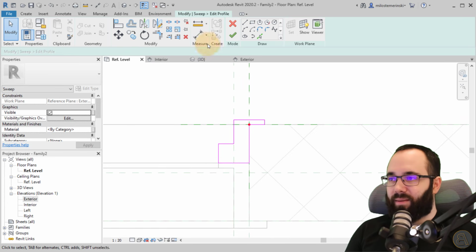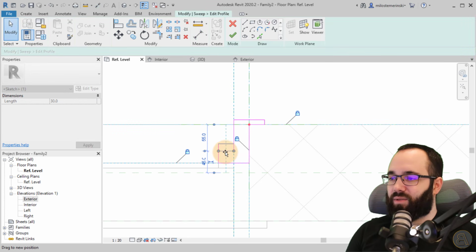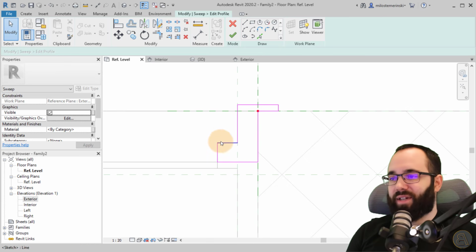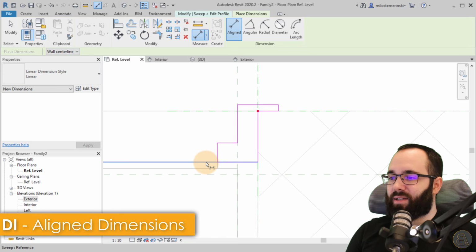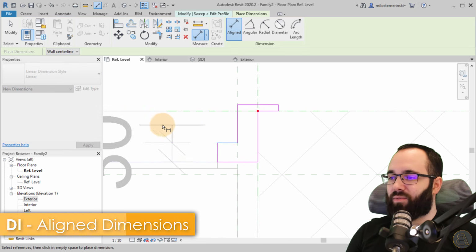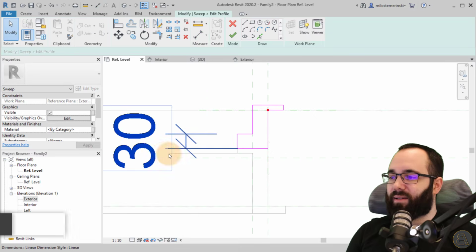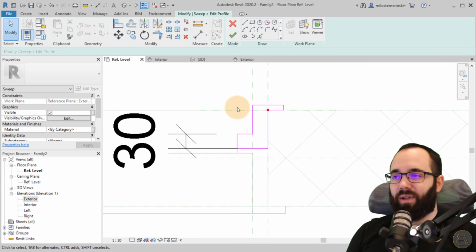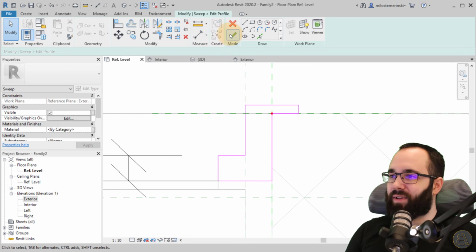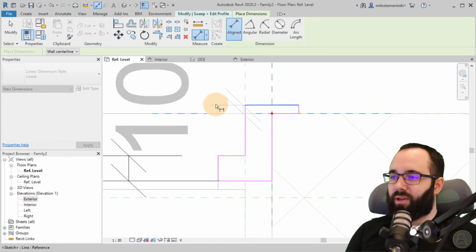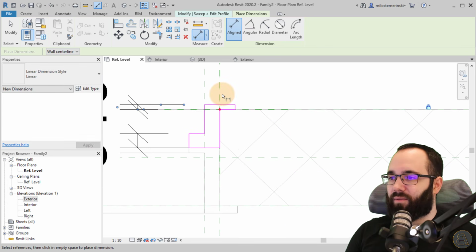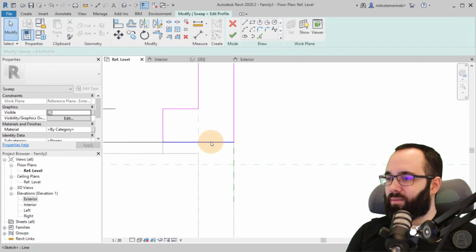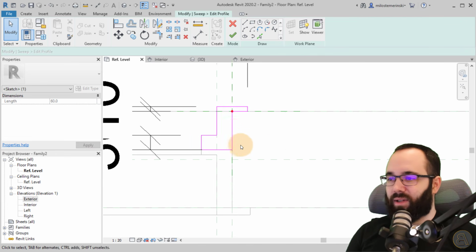And then for the rest of them, for example, for this one, actually I want this to be closer to the window, or closer to this existing interior side frame. So what I want to do here is just dimension this in such a way where it's basically locked to that frame, so it basically moves with the frame when the thickness of the wall is changed. And now for this side here, we can just go from here to here, and then for this we can go from there to there. And I think that's it. Did we lock in this one? Yes, we did. Okay, perfect.